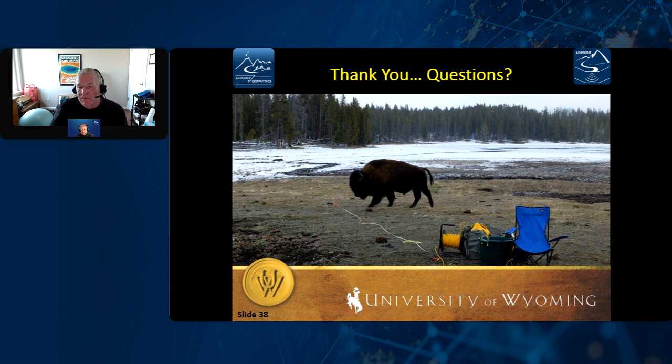Now, in terms of the shot itself, because these were pretty shallow and we wanted high frequency, we did some supporting modeling with the velocity profile that we estimated from previous refraction data. We wanted to be around 400 hertz nominally for our reflection signals. And so we ended up using a sledgehammer, honestly, which is not going to be useful for this summer when we're going deeper. But for this particular site, we could afford an impact source, and we would just basically hit every other station, so it would be a 4 meter shot spacing.